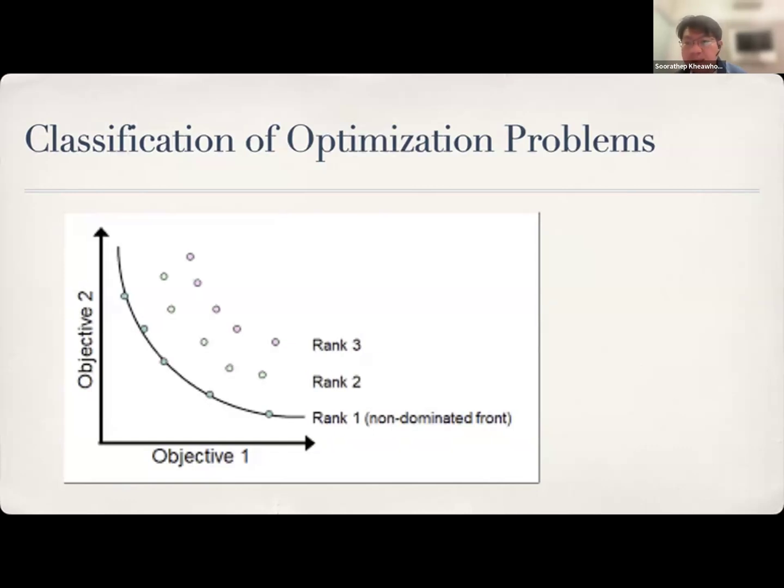You don't have an idea of the size of the weighting parameters. But if you solve for the non-dominated solutions first, you see the range of each objective, and then you can find more information about the importance of each objective function, and assign appropriate weighting parameters.